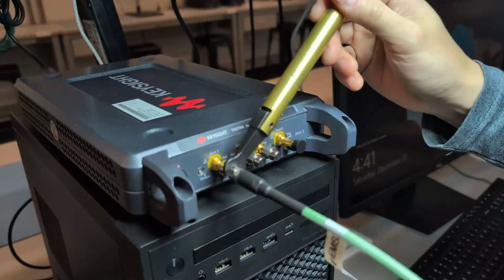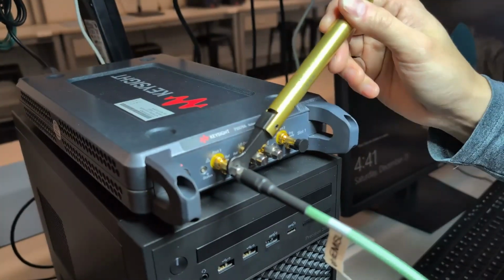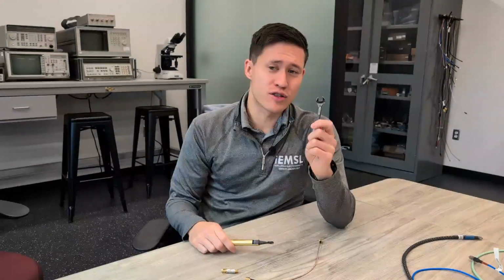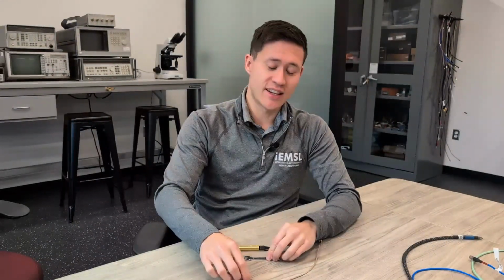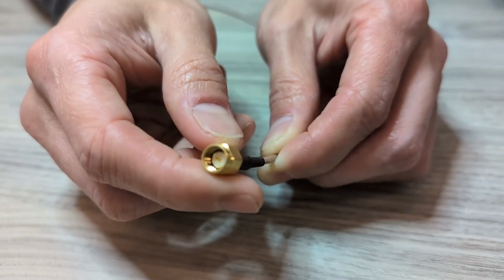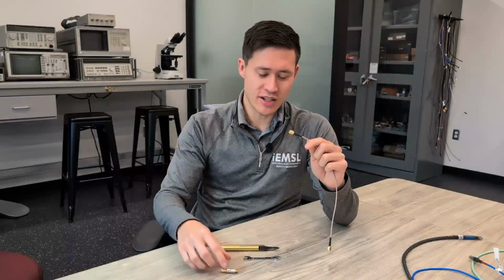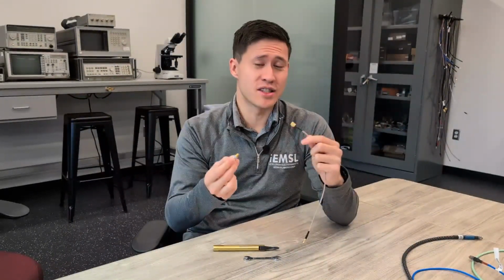Once your connection is hand tight, use the torque wrench to continue to tighten the coupling nut until the handle breaks away. In order to hold the other connector stationary, you may want to use an open-ended box wrench to provide counter torque. When it comes to making connections between any set of connectors, the only thing that spins is the coupling nut. Now, this is incredibly important because if you try to spin the entire connector, you'll end up causing damage to the conductors inside.